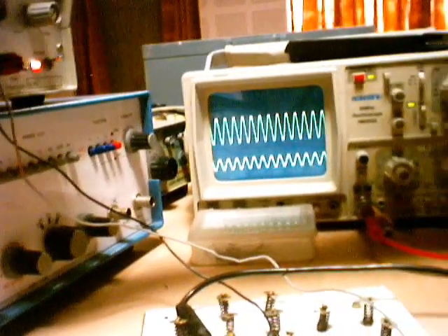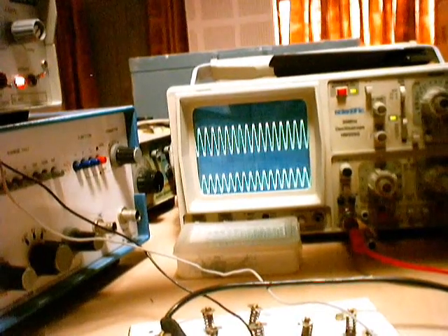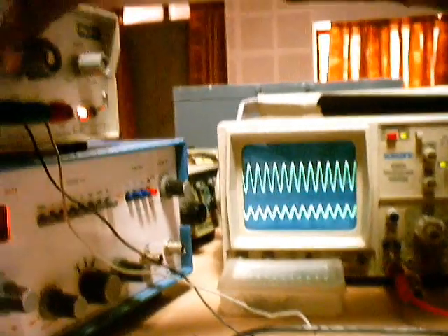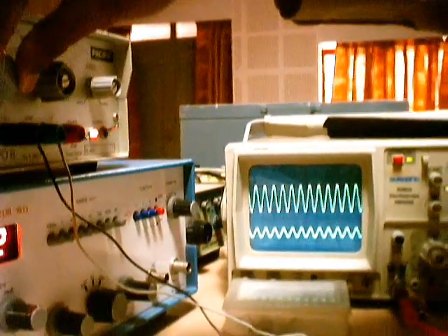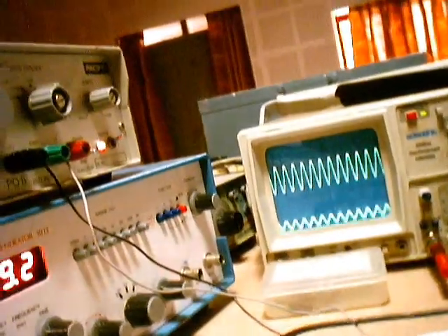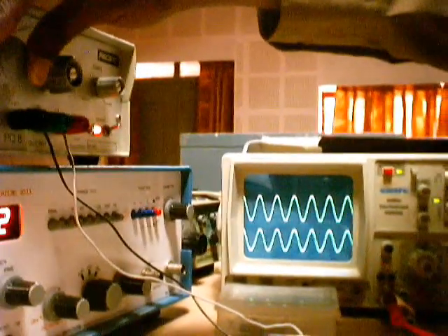You can see the output has started reducing. Here you can see this is the minimum value. If I slightly go beyond this, the output voltage increases again. So you can easily identify at what frequency it is minimum. This is the minimum amplitude, which corresponds to F0. The corresponding frequency we can get either by noting the time period of the waveform, or from your DSO. So let us identify where it is minimum.